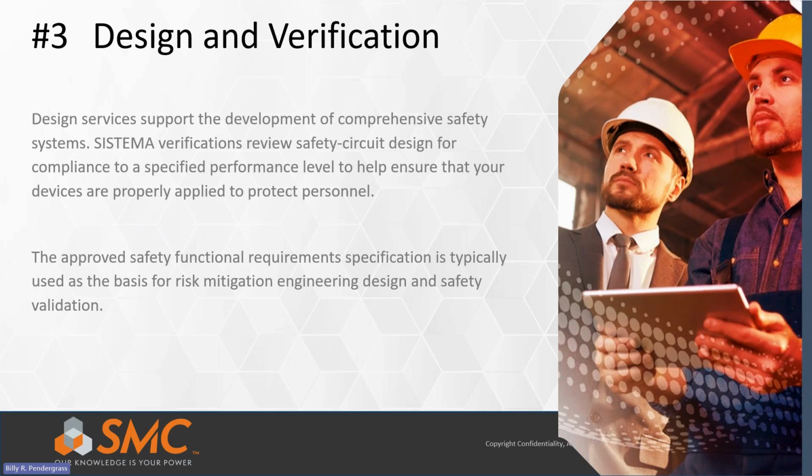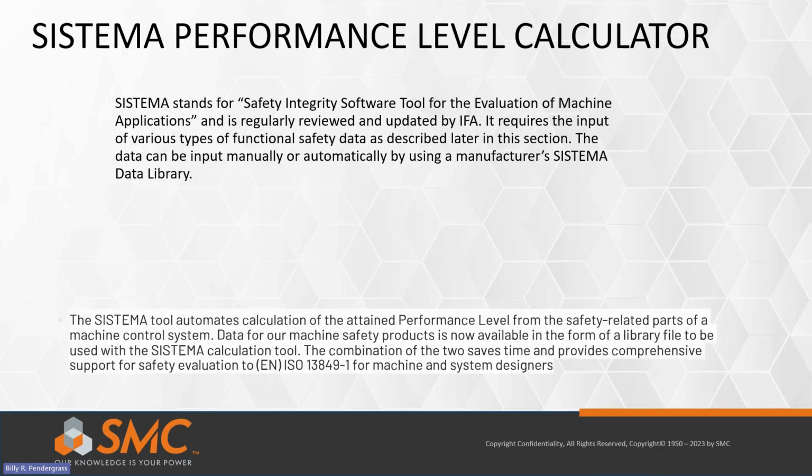Let's get a better understanding of SISTEMA now. SISTEMA stands for Safety Integrity Software Tool for the Evaluation of Machine Applications. A SIL, or Safety Integrity Level, applies to a safety function. The subsystems that make up the system that implements the safety function must have an appropriate SIL capability. This is sometimes referred to as the SIL claim limit, or SIL-CL.